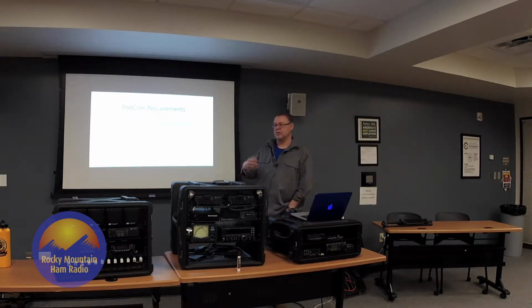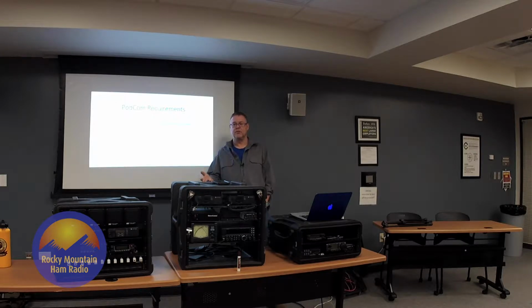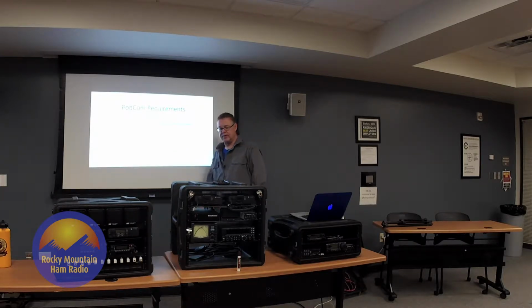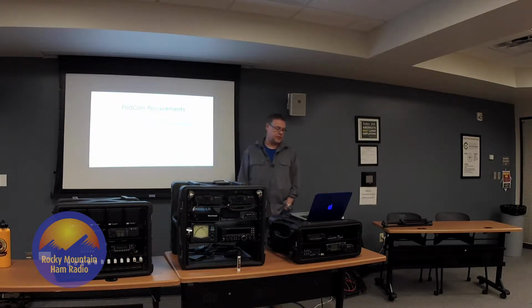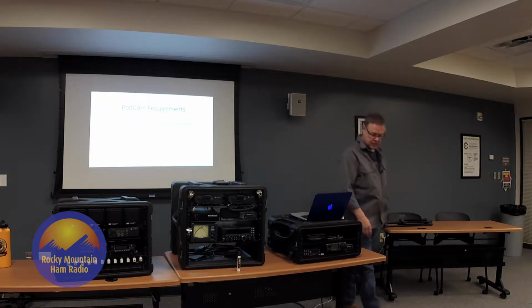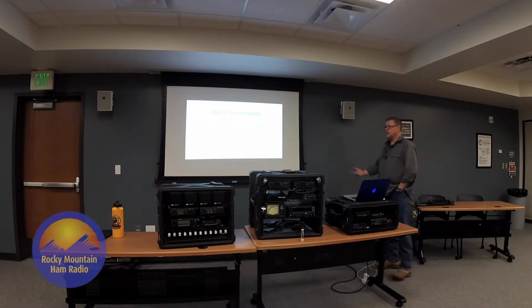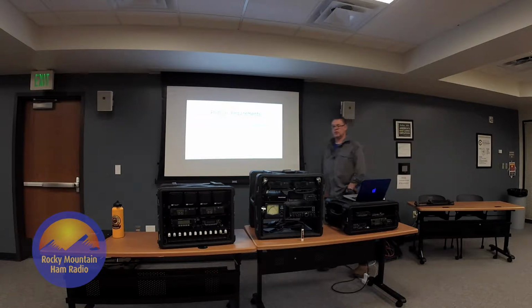This will drive the design of your radio selection and everything. Do you need digital modes? Do you need modems, TNCs, sound card interfaces and such as these items right there? Do you need antenna tuners, or does your radio that you're going to use have an antenna tuner? If it is, can it go past 2.1 or 3.1 to 1 and still tune?